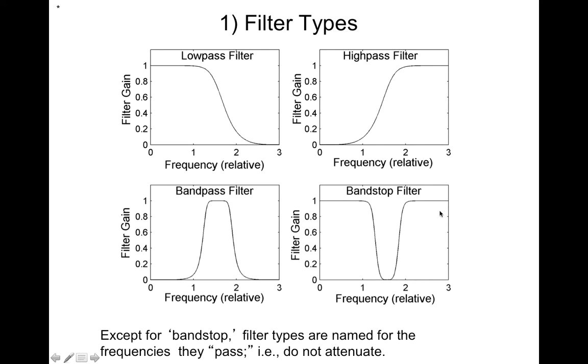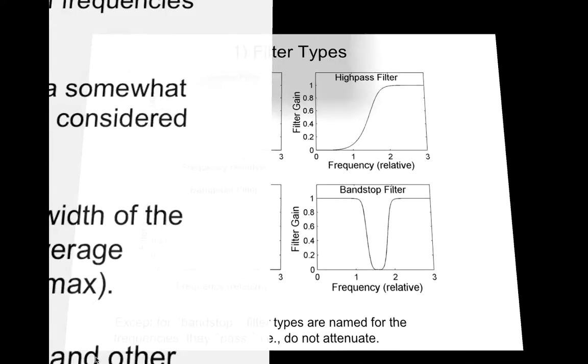The band stop filter is often used if you know a particular range that's going to be troublesome. So for example, if you're in a typical signals lab, you're going to have noise at 60 hertz because of the power levels in the room. So 60 hertz noise, often you will see a band stop filter centered around 60 hertz. So that's a fairly common thing.